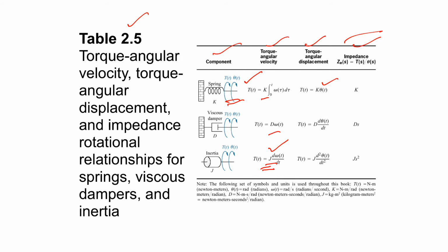Then holding the body still, we rotate the adjacent points of motion one at a time and add the torques due to the adjacent motion to the free body diagram, and this process is repeated for each point of motion. So for each free body diagram that we obtain by keeping others still and taking one into consideration, we have one set of differential equations.